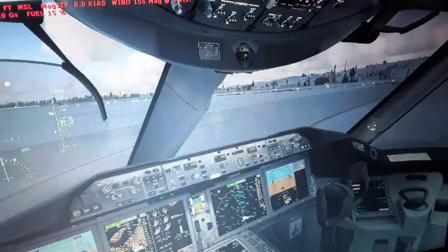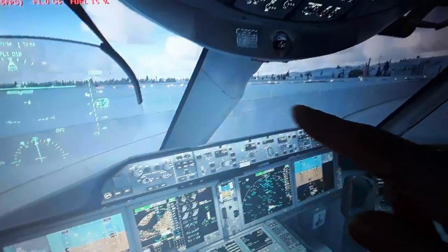If you have a failure, we're going to lose the auto trim function from the autopilot flight director system panel. The auto trim is important because the aircraft trims itself automatically. You can also use manual trim. So we have a failure that degrades the flight control computers, like in the Airbus aircraft. We have something in the Boeing we have to do.